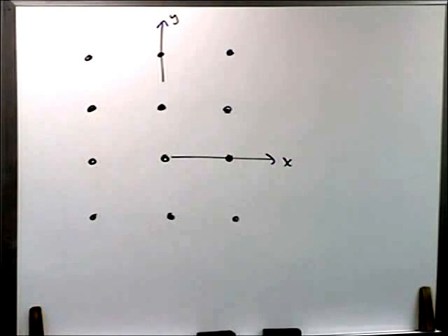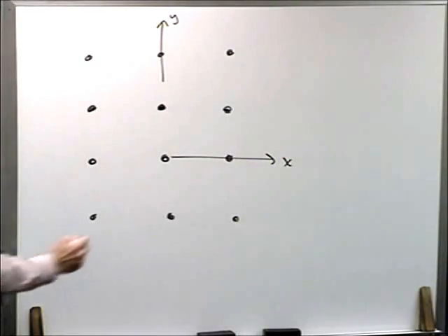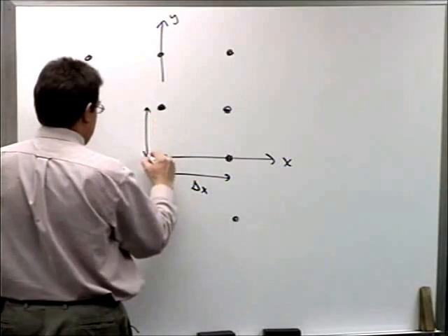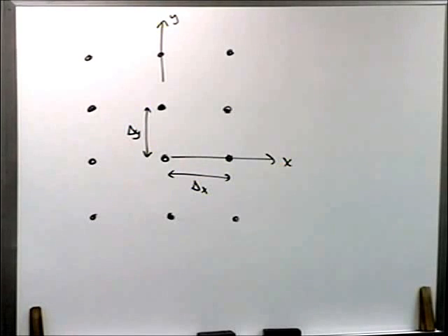You're going to work with the voltage here, here, here, here, and so on. Okay. Now, what this differential operator says is, well, the second derivative of v with respect to x squared plus the second derivative of v with respect to y squared, we need to approximate those derivatives based on this kind of grid. Okay, so let's say we had equal spacing throughout the grid here, where delta x is the spacing between grid points along the x-axis, and delta y is the spacing along the y-axis.